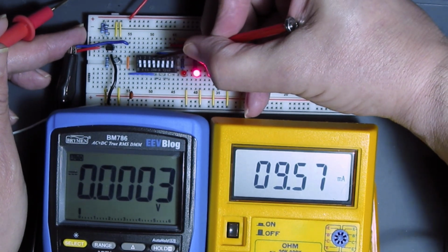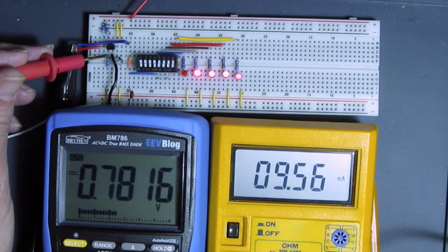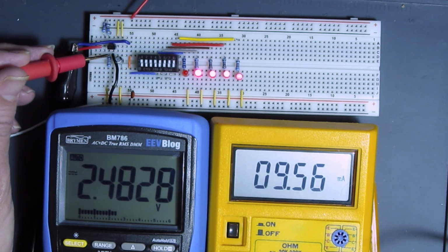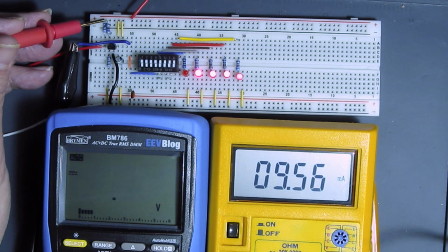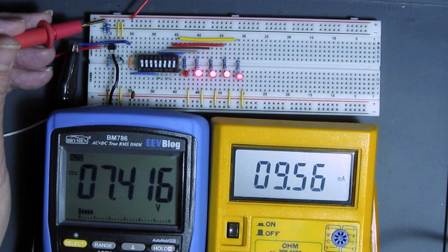I'll start by measuring the voltage on the reference input. 2.48 volts. Almost 0.8% low. I'll need to keep an eye on that. What's the voltage on the 7.5 volt rail? 7.41 volts. That's saying the divider ratio is about 0.4% off, in the same direction. Those two between them account for the 1.2% or so that we're seeing.